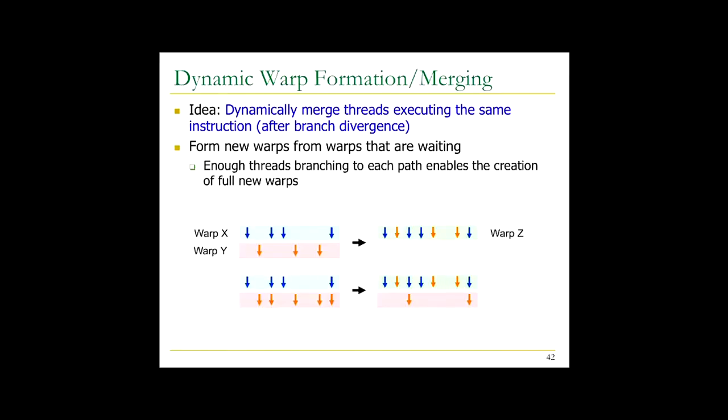If you look over here, it's not as perfect, right? Here, what happens is you have these warps that are active, and you want to combine them with this other warp, these threads that are active, the blue ones. These orange ones are also masked. They have their mask bits set to 1, so they're active. Now, how do you combine these two? You can fill in the blanks over here, but you cannot fill in the parts that have blue because you already have a thread over there. Right?